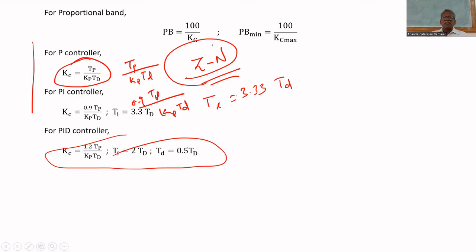The process is at steady state at 50%. The set point is 50%. Now I can transfer from manual mode to auto mode and leave it. Even if it takes one year, the controller will control at 50%. Whatever disturbance comes into the picture, the controller will take care of it. So this is called modeling, tuning, and closed loop control.